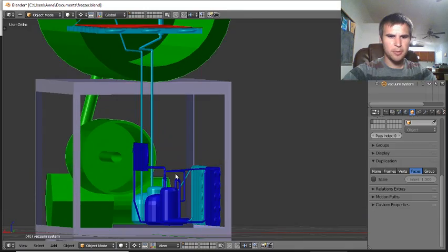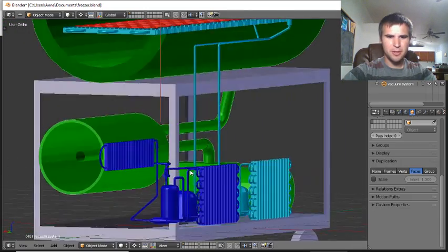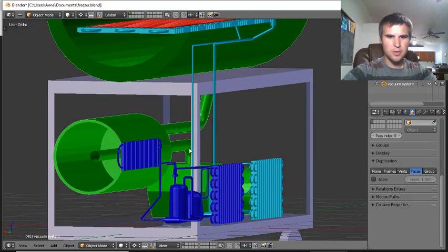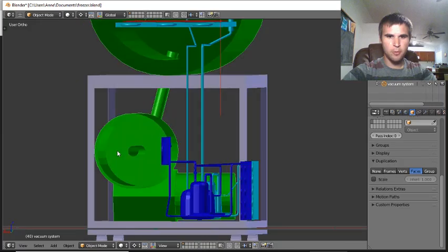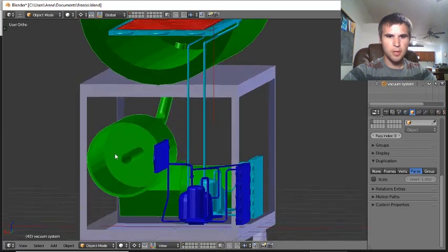So then the cold trap, I have it drawn real simply here, as just the vacuum tube comes down into the center. That will force the material as it enters the trap up through here, and that'll force it to kind of mix around and move throughout the entire device before it actually goes down the tube.